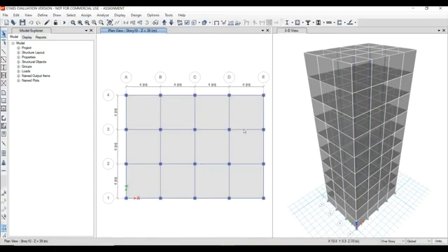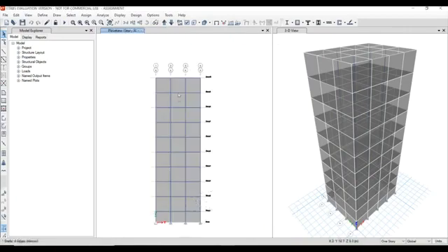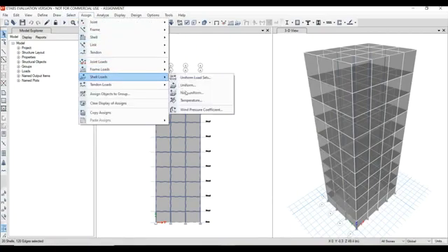And now we need to add wind loading. So to add the wind loading, go to elevation view of section A. Okay. And in this section A elevation view, now make sure that you turned on all stories from right bottom and select the shells of every shell in the section A. Now click on assign shell loads